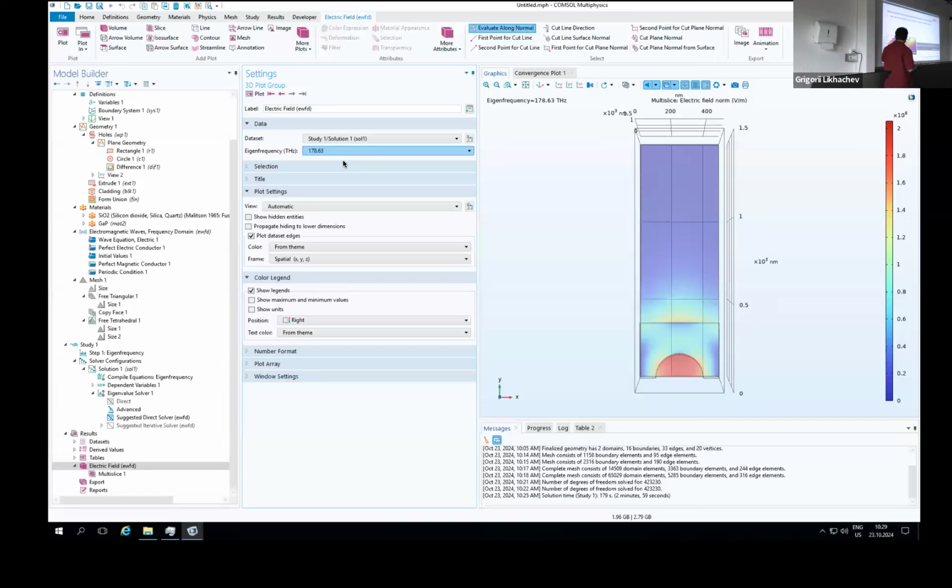These are two color maps. Here you see the center frequency, here you see the band gap, how big it is. What you need to do is start from a high frequency and bring down the band gap. Why is that the case? For the FSR of the resonator, we know for anomalous dispersion the FSR should become larger in frequency. If it gets smaller, it's normal. In a ring resonator, you play with the group index n_g, which depends on the cross section. Here, you play with the length.